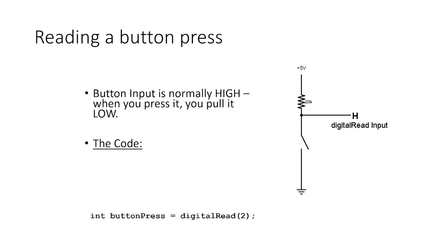We just need to create int buttonState and equate it to digitalRead, to read the state of the button, digitalRead button. Are we together up to that point? Any question? If you miss it at this point, I think you're not going to be okay.